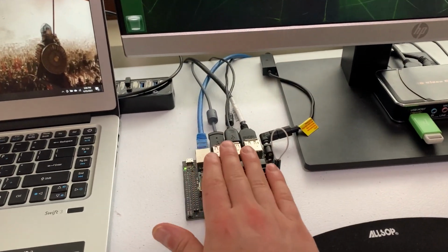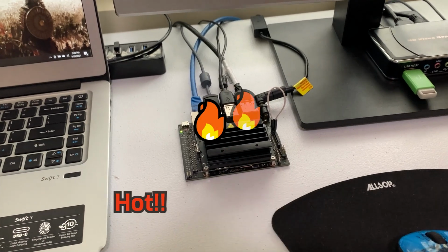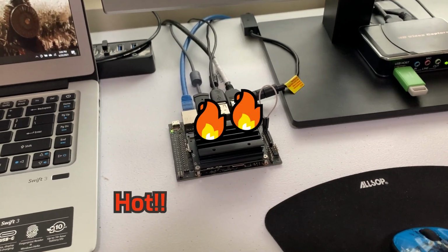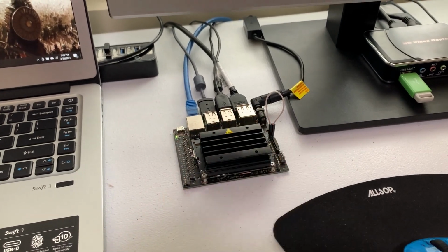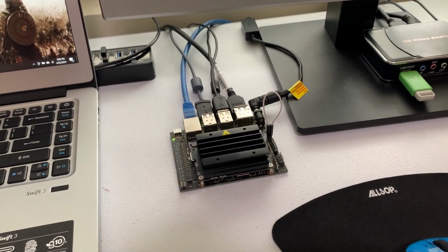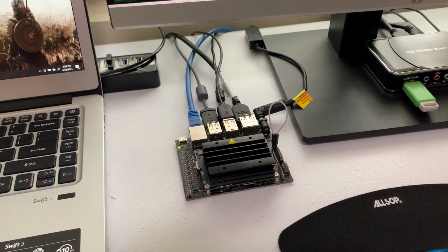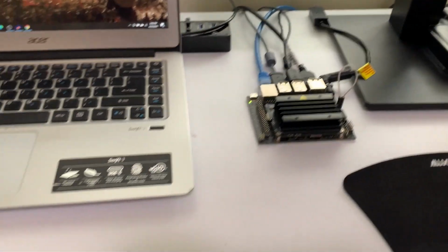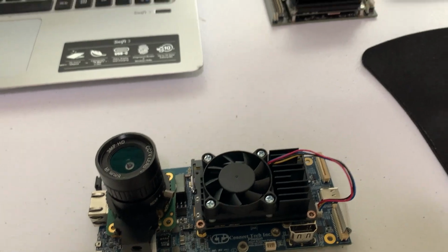First, pause and carefully feel the heatsink on the Jetson Nano, and you'll notice that it's getting pretty darn hot. That's because Mastcam uses lots of processing power and dissipates a lot of heat. Fortunately, the Nano will throttle itself or even shut itself down before it gets too hot. If you want to run Mastcam for more than 5 or 10 minutes, you'll need to get a heatsink with a fan like this one, which we used on our Mastcam prototype.